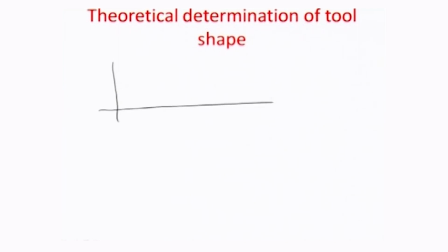So, let us look at what we did in the 2D case, just reviewing what we said in the last few lectures. Supposing there is a certain tool surface, for example this is the tool surface, and also the workpiece surface with a certain topology which is mapped by some function, let us say y equal to phi of x, and these are all the so called workpiece coordinates.